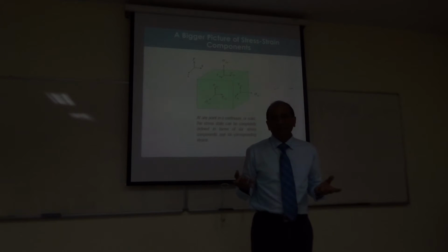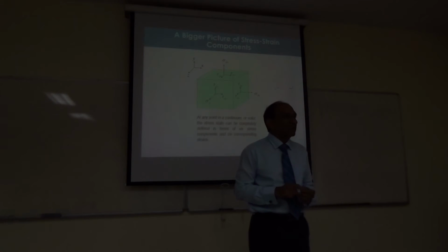So right away, when we talk about E, what E are we talking about? Which stress over which strain? That means there must be 6 E. There could be 6 E for a material, for each direction, depending upon which stress you are dividing by which strain.